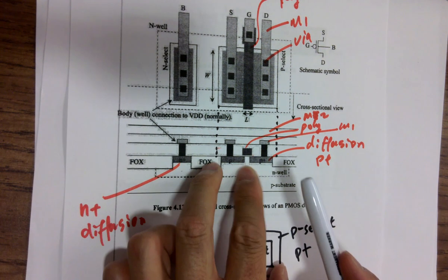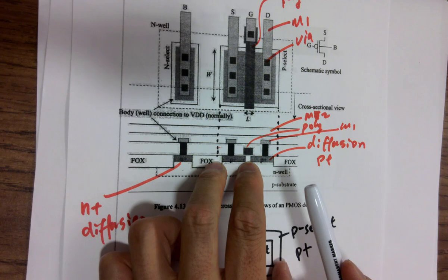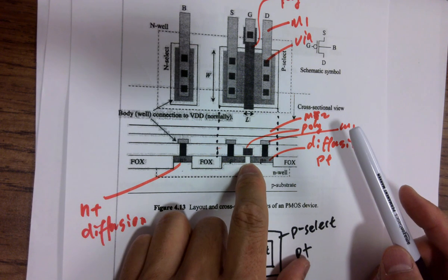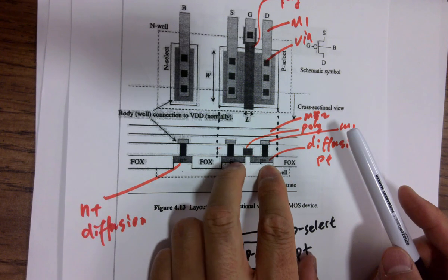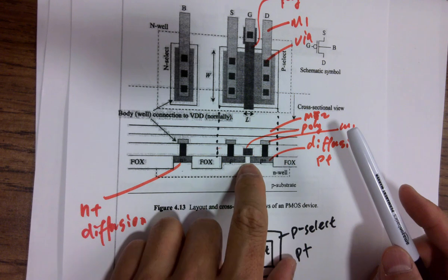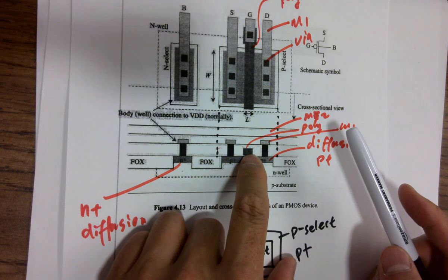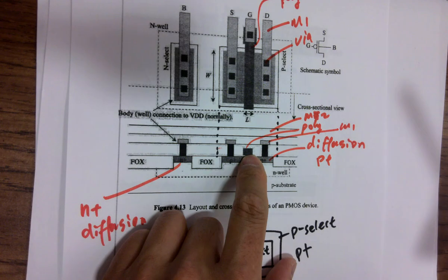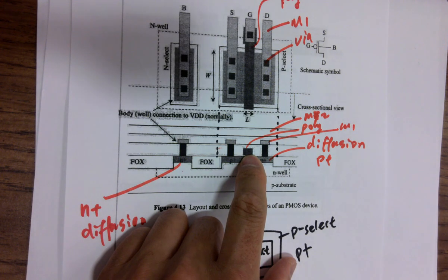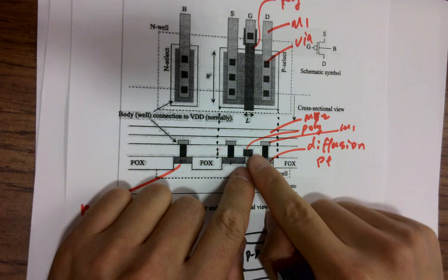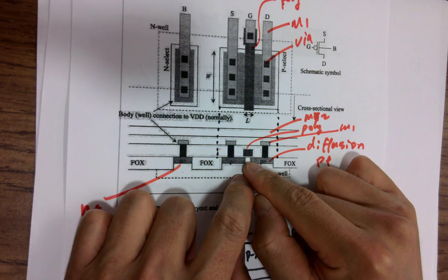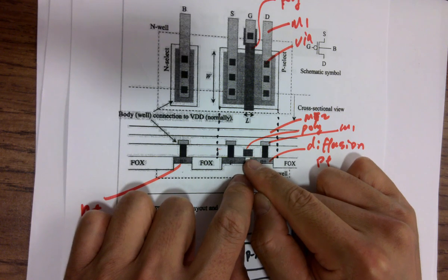Imagine you want to do this accurately, have a little P plus opening here and define a certain gap, and move it to the right-hand side, and then dope this area. Instead, you have a homogeneous layer of poly, and then you etch it away from the rest of the wafer, and you just leave this wire on the top. So we leave this wire on the top, so we get a gate directly on top of the opening, of the gap here.